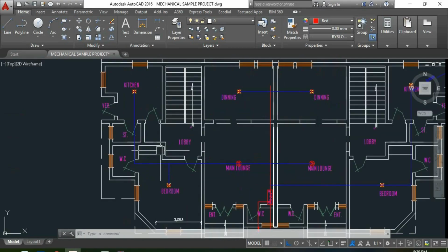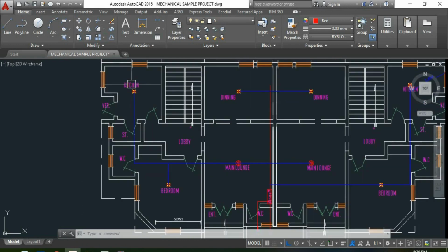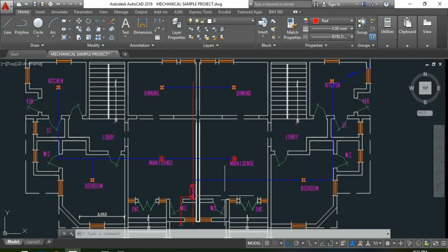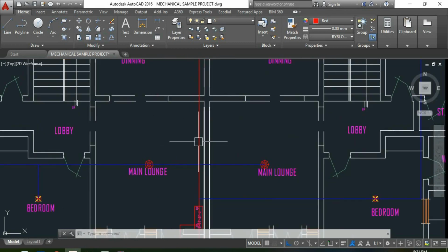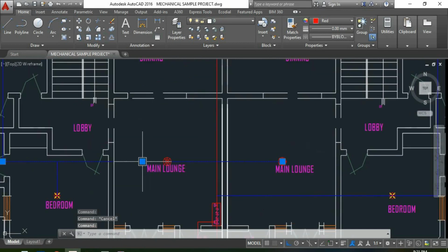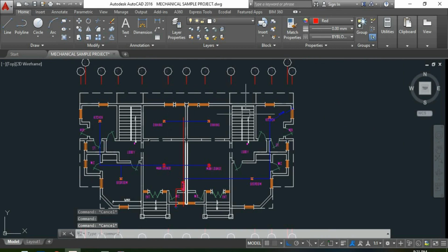Having specified our sprinkler heads, where we distributed the heads into different spaces in our project, we've designed the piping configuration, which for this project is a tree configuration, where this is our main pipe and all these blue are our sub main, or you call it cross main, or branch pipes.